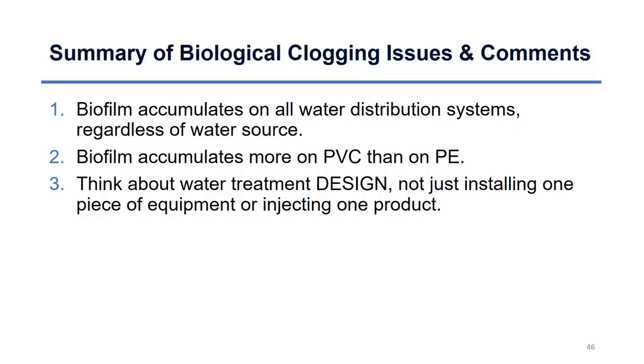Every time you have a storage tank, you can control the flow rate. The slower the flow rate, the more contact time you can have. The smaller you can have a treatment system. You don't need to have a massive treatment system that goes at a high speed or a high flow rate. So think about that as you're thinking about water treatment design.